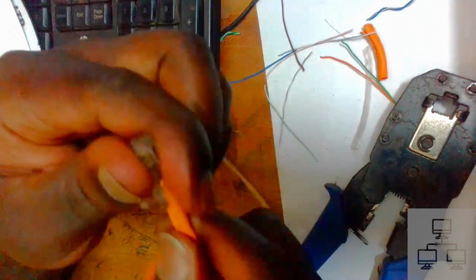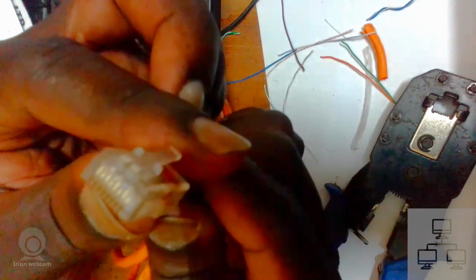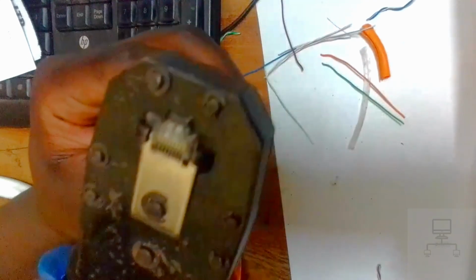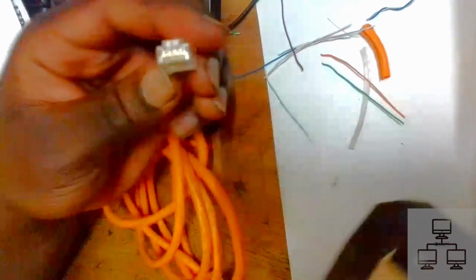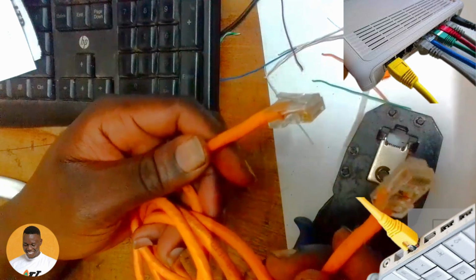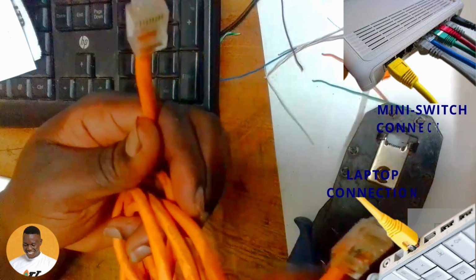That's why we have to face the noses of the RJ down, so that from both sides we can see through that RJ and we see all the wires reaching the extreme of the RJ. Then after we secure them using our clipping tool, and we think at this point our cable is ready for use, and we believe that this is going to work. Yes, it's going to work.